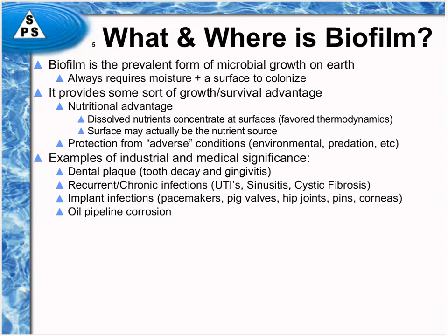The water is always on the bottom of the pipe, and with the microbial action being in the water part of the pipe, it's very common for oil pipelines to corrode, and you guessed it, right on the bottom of the pipe. So oil pipeline corrosion control is a very important thing to do, especially for environmental impact.